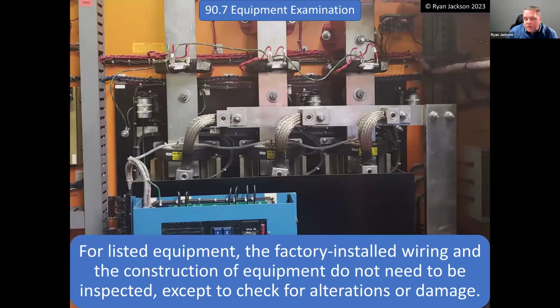For listed equipment, the factory installed wiring and the construction of that equipment does not need to be inspected, except to check for alterations or damage. All right, so I don't need to get into this piece of equipment with a magnifying glass and start figuring out, okay, what kind of wire is that? Is that THHW or is that THHN? We don't need to do that. It's a listed product. That means it's already been inspected, right? We just want to make sure it hasn't been altered or it hasn't been damaged.